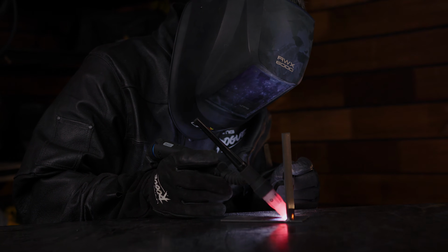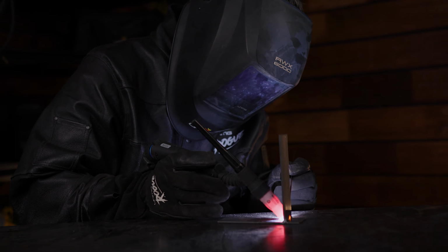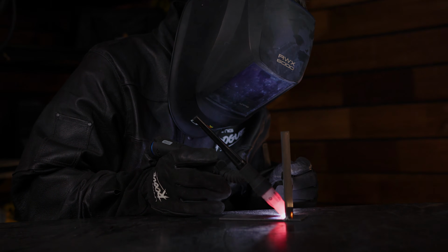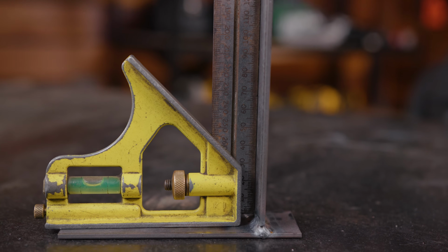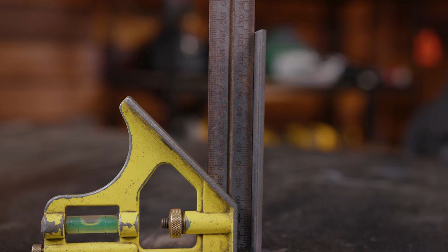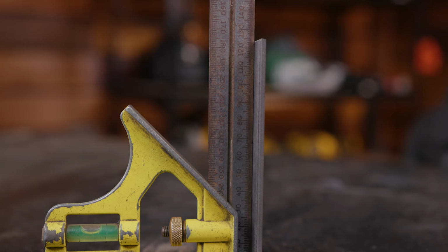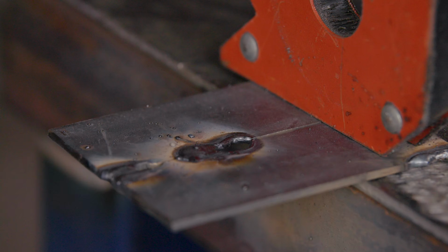Weld on both sides, as the metal will often pull towards the weld. Welding the opposite side will pull it back. Clamp your piece correctly. Use turnbuckles and lots of clamps if needed. Also use lots of tacks. Metal is always going to warp, even if it's just slightly, once there's heat in it. The important thing is to minimize the amount of distortion, especially on critical welds. If you do end up with warped metal, you can go back to reheat it to fix it. There are plenty of ways to reshape it, such as using a hammer and a dolly.